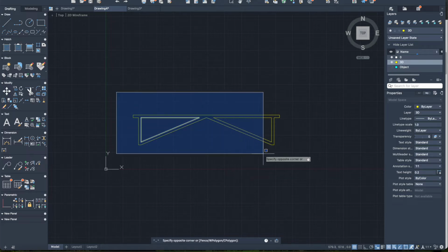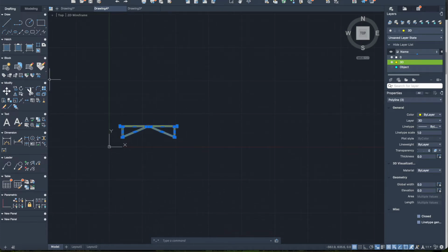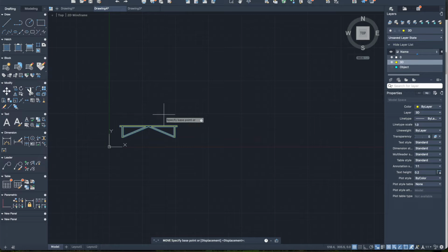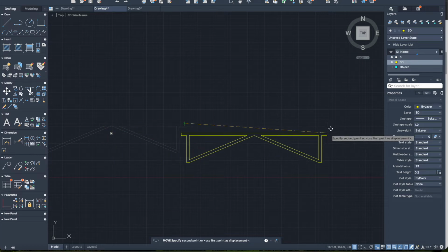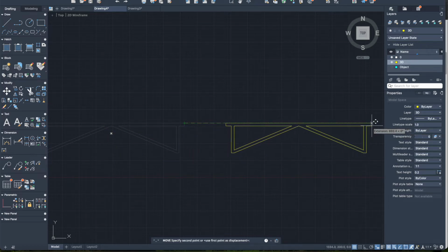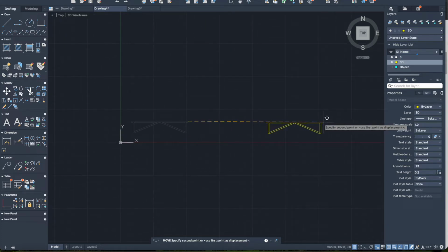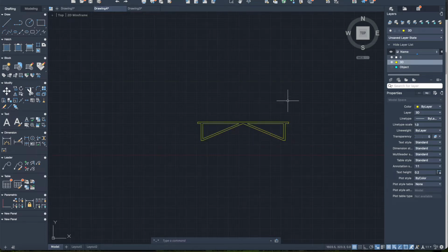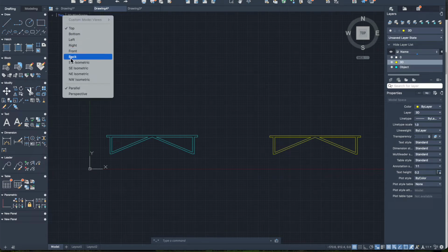And then we can select our bridge. Now I recommend you zoom out so that you have the ability to pull. And then we select the move tool. And pull it across. It might be easier to do this in ortho mode if you're really struggling. Okay, so once we have it in position, we can turn on the object layer again. To proceed to the next step, you would want to change your view from top to southeast isometric.